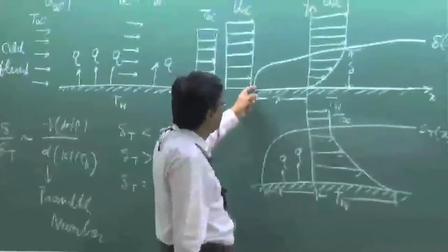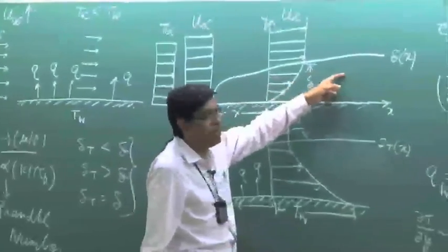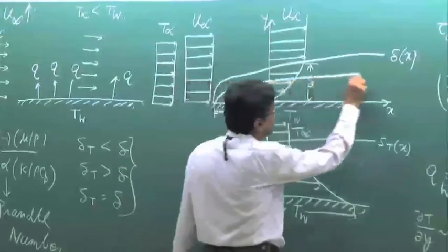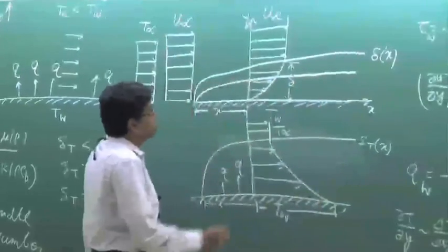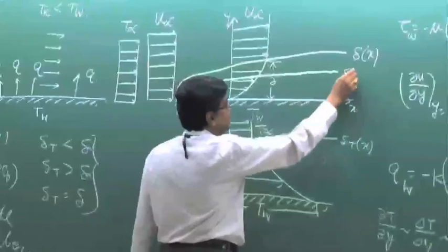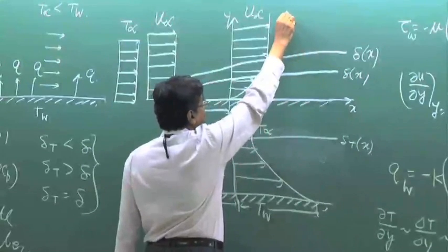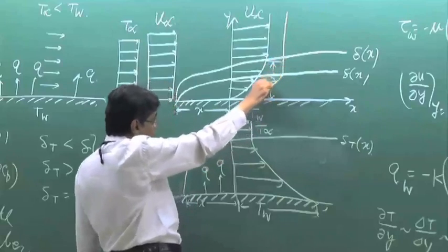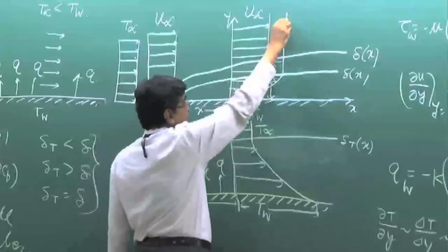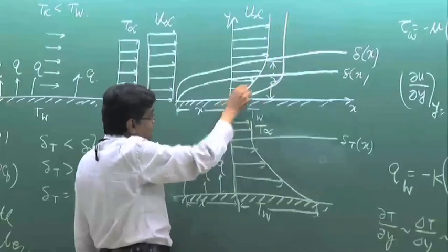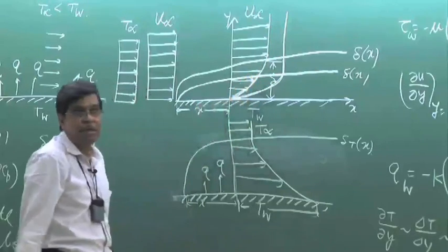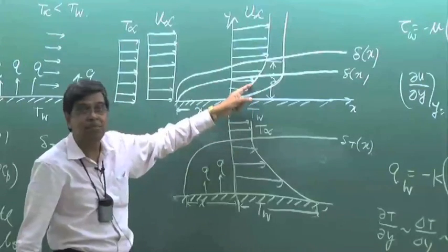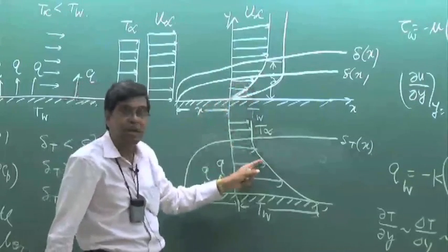You can find it geometrically also. Here, if you draw a boundary layer which is lower in thickness, for example in the second case the boundary layer thickness is reduced, and also your free stream velocity is increased. So you see, this will be your velocity distribution, and this curve is steeper than this curve with respect to the y-axis. That means del u del y for this curve is more than this one. Similar is the case for del T del y.